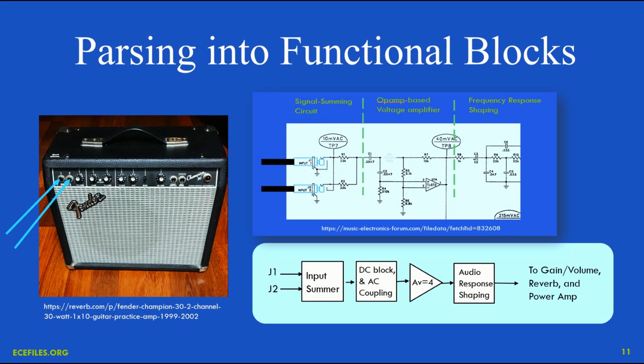So after we figured that out in episode 3, we labeled this first section of the circuitry the signal summing circuit. And we drew a vertical line here because this circuit is really separated from the next one, which we also covered. It's an amplifier. We'll review that later in this episode. But the important thing conceptually is that we can draw this line here, and we can do that because this second circuit did not load the first circuit significantly. So this summing circuit works the same whether we connect this next one up or not.